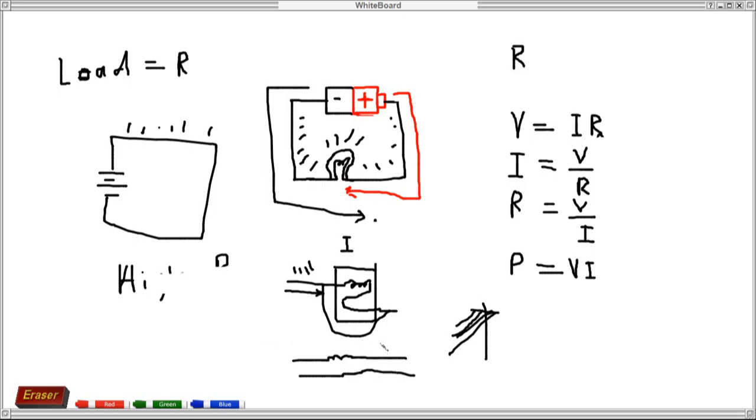One works via current: the current that flows through heats up a thin wire until it melts, because the thin part can't tolerate a certain amount of current, so it blows out and cuts the circuit.